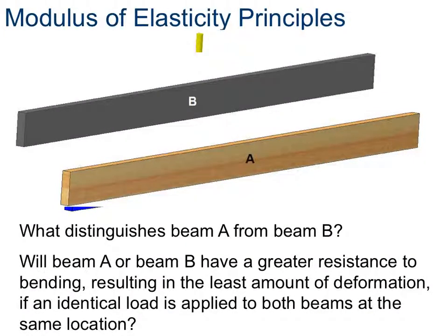Okay, so they're just asking you the same thing. We're putting the same load. If we had them sitting on things here, which one would bend the least? Now, if you don't know this, wood would actually be stronger than plastic, because it has a higher modulus of elasticity.